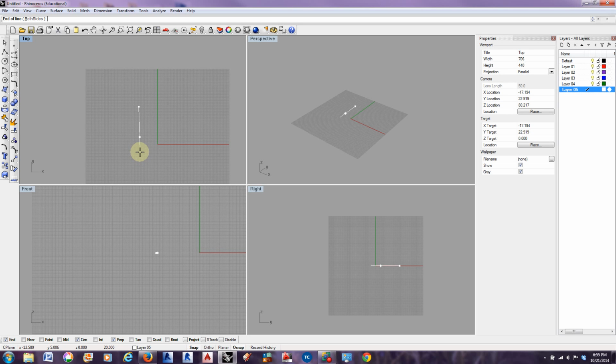And so you can draw this in any direction you want, but if you want to start using ortho without having to select it, you can hit the shift key and it starts to snap to vertical and horizontal. So that helps when you start to draw things, so you're not getting a line that isn't quite straight. And then to finish it, you keep holding the shift key if you want it straight, and then click to end the command.